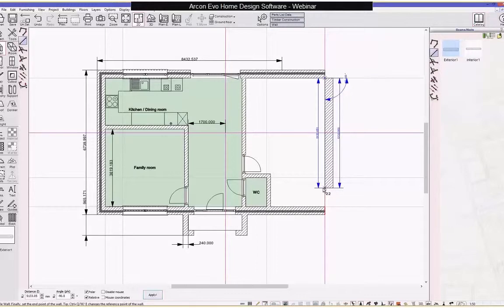You've also got numeric inputs. You can obviously enter walls numerically. If you've got an existing plan as well, for example from a DXF or DWG file, or from a drawing as an image file, a JPEG or a bitmap, for example, you can also import that in, and that works as a background where you can overlay and draw over the top of the actual background layer, so you can very quickly draw out your plan using a background image.